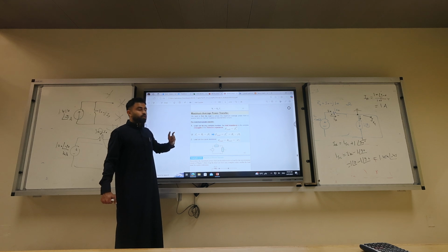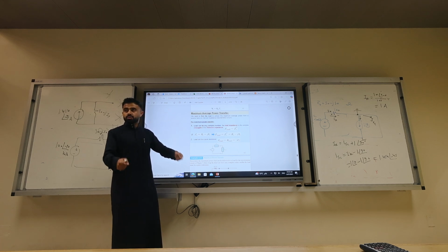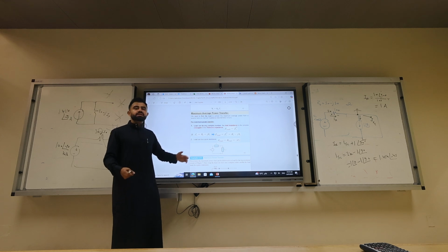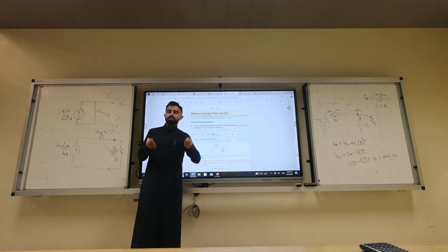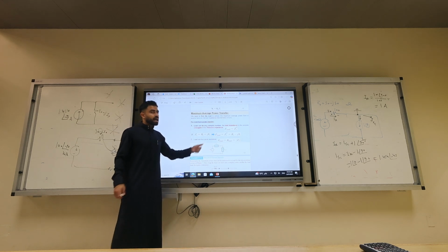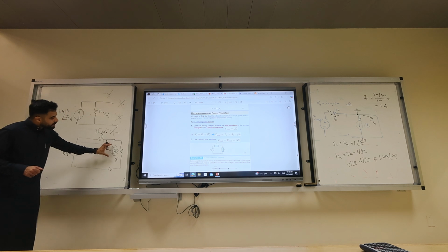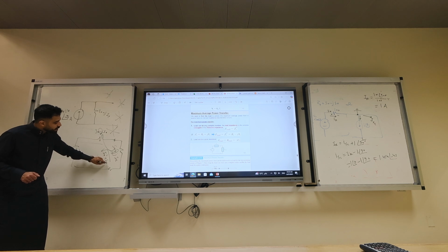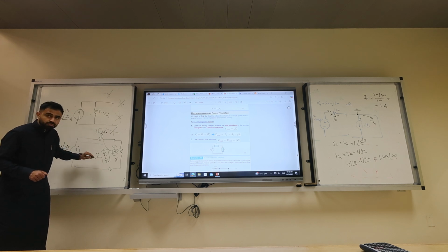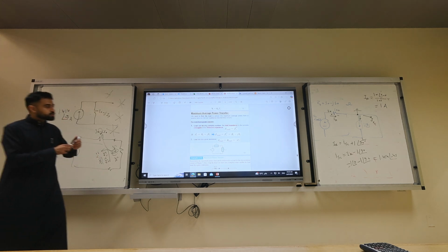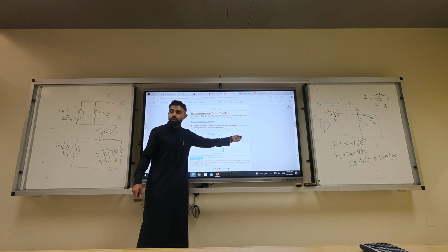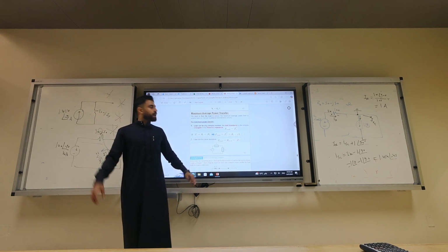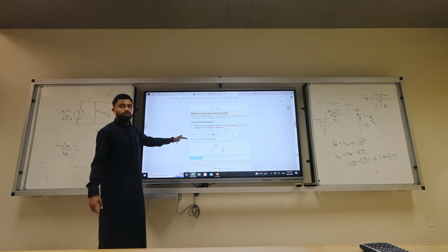Now, also, if I'm allowed only to connect resistors to the system, why we say that? For example, if I'm only allowed to connect heaters, then there is another formula. Instead of connecting 50 plus J50, I connect 50 square plus 50 square, square root of, which is 2 times 50 square. So if I connect R square plus X square, if I want to have only resistive value, there are two options for maximum power.